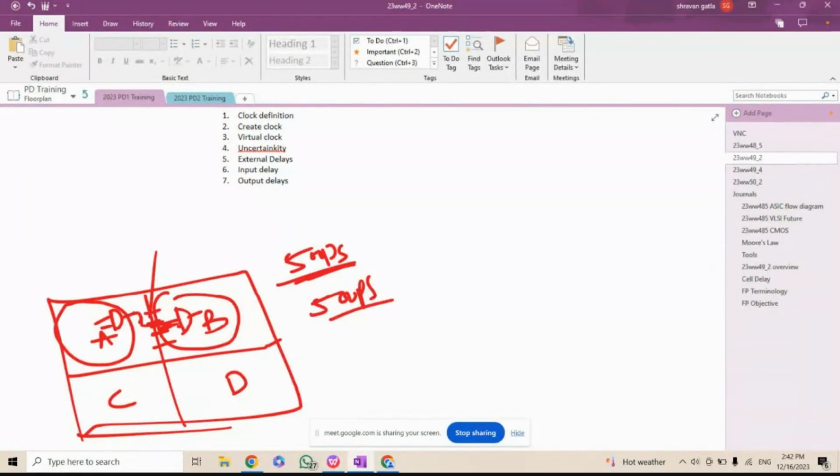Let's say you will route this, and you will get some RC delays, and you need to buffer to fix the tran violations. In that process you will see some delays. So if they don't give you some delta, then you will see timing violations.